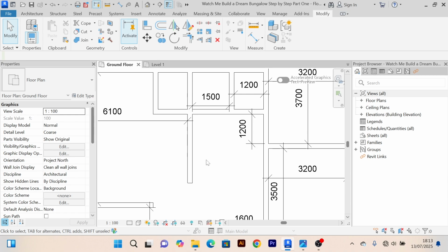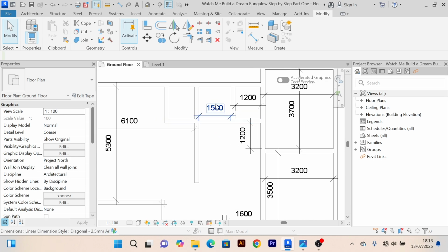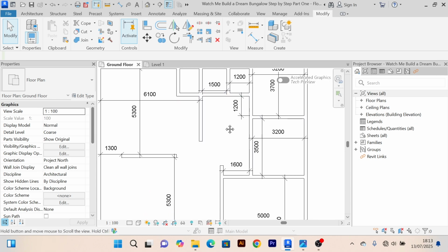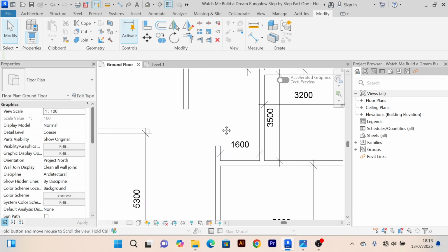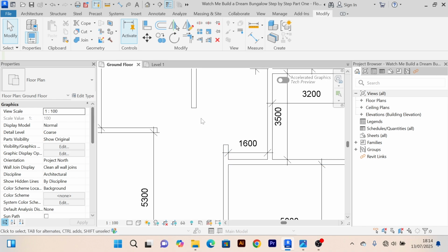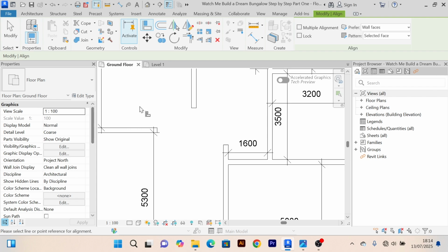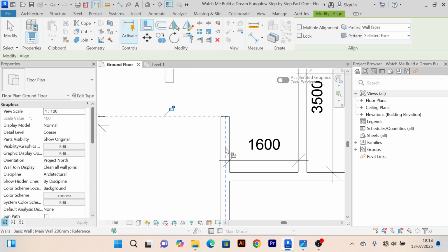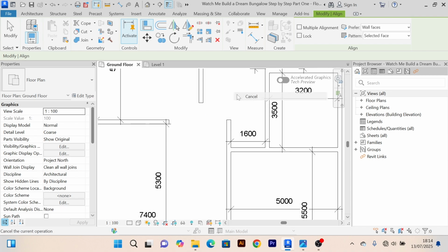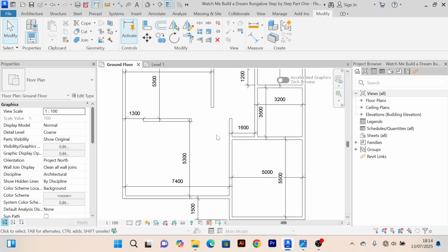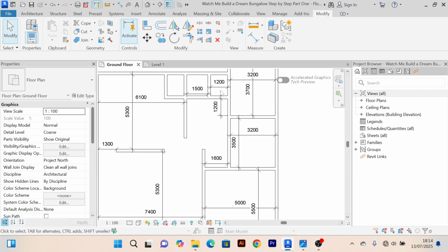You need these kind of walls to create what we call privacy for things like the washroom, the bedroom. They need a lot of privacy. That's why we have such. So I'm going to push this wall to align with that one. You come to your line tool like that. I'll click on this line, then I'll come and click on this to take this one there, so that they're perfectly aligned. So anyone around here cannot see from here.